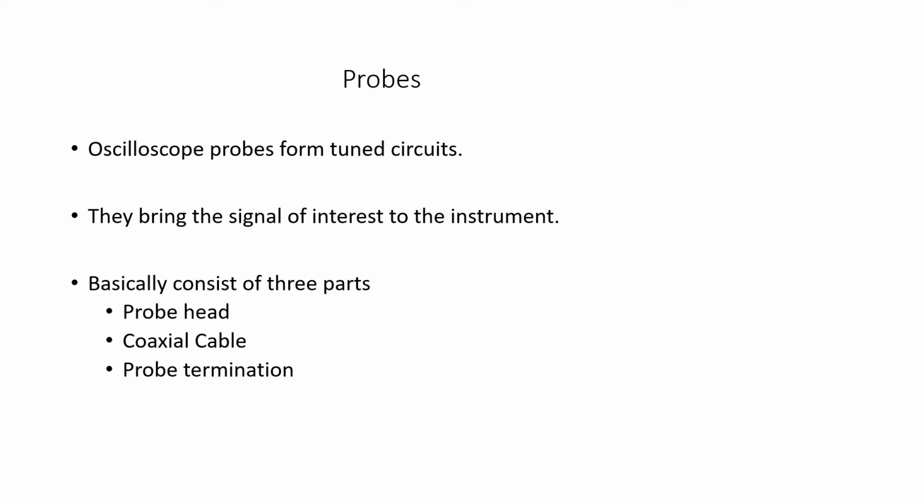Next, a passive voltage probe or a high impedance probe. It is a 10:1 attenuator. Oscilloscopes are typically used with a 10:1 probe. Active probe: one useful probe is the active probe, which achieves a lower capacitance without the attenuation associated with the 10:1 probe.